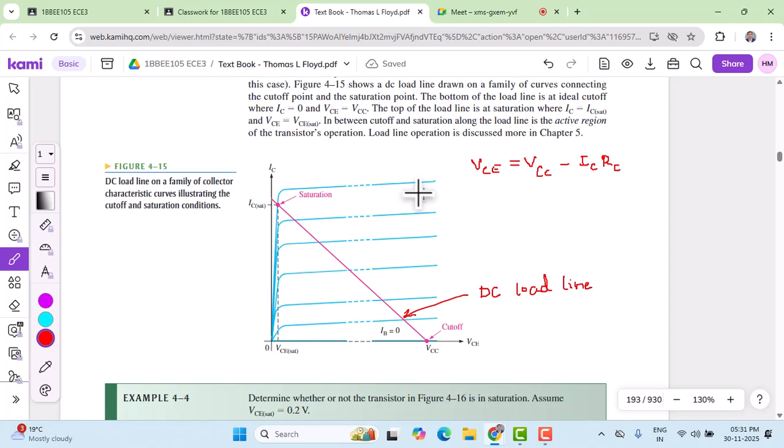If the applied voltage or applied current exceeds the PD max, then we are in the unsafe region of a transistor. With that, we have a formula here. Since there are two variables in this equation, VCE and IC, if we assume VCE is maximum, then we can estimate what the collector current must be so that the PD max is not exceeded. That can be estimated using this relation.